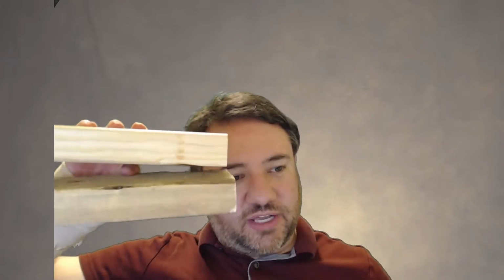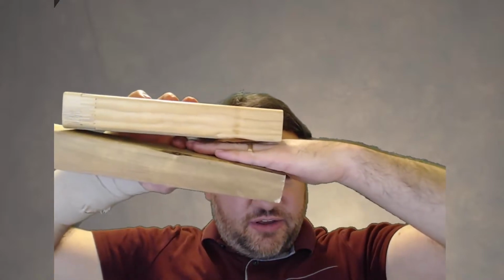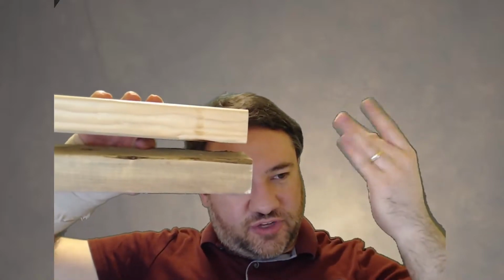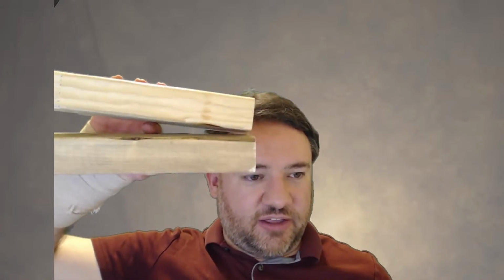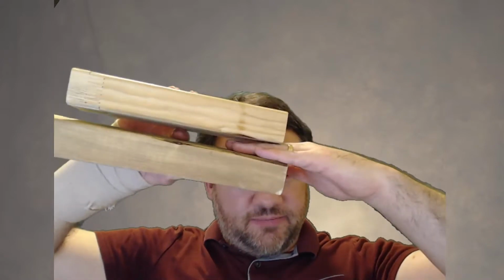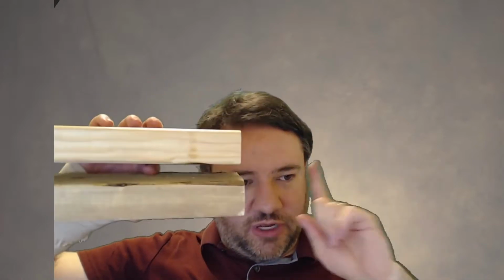Okay, so then how am I going to know when the connection fails altogether? Either this one could fail, so this one could fail in row shear, or these two together have to fail at the same time, so the sum of these two. If either of those things happen, then the connection is going to fail in row shear, right? I mean, obviously my other option is that I could have a yielding failure, where I only have one yielding failure calculation for the whole connection, or I could fail in group tear out or net section, which we haven't talked about yet.